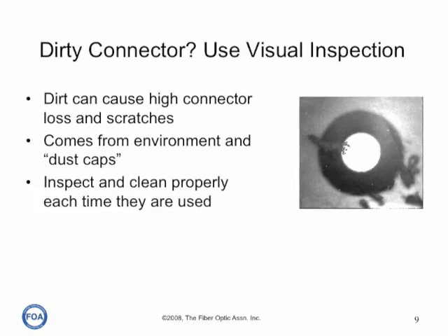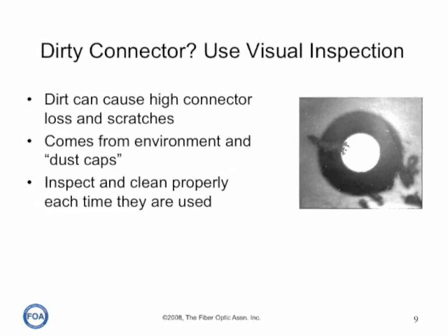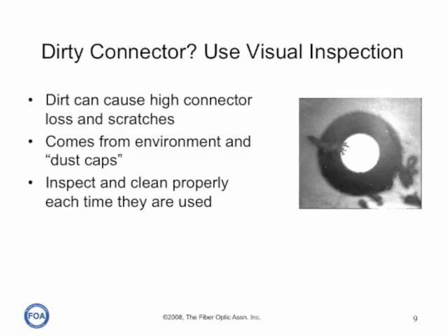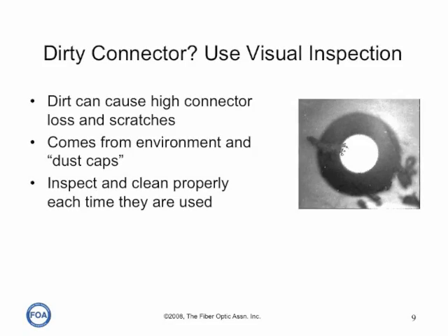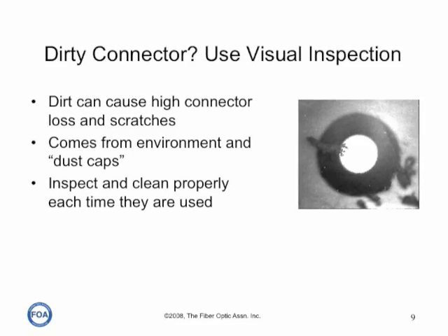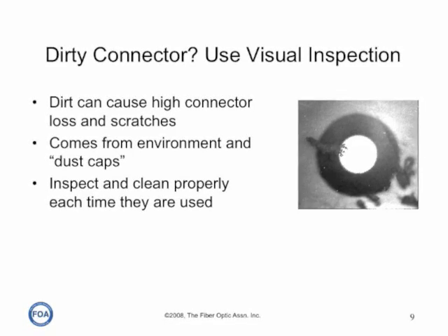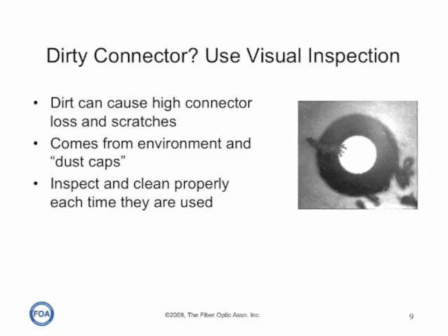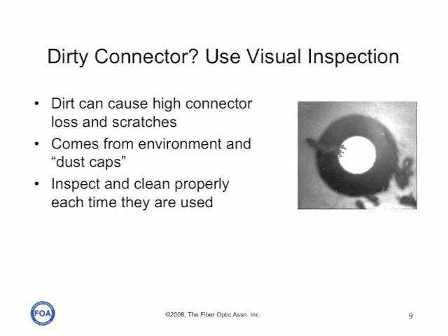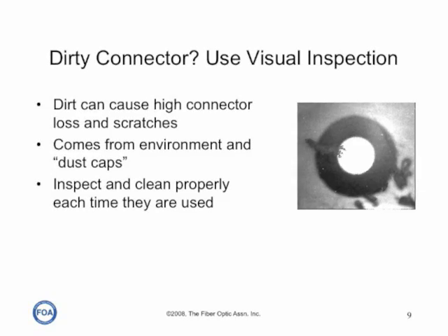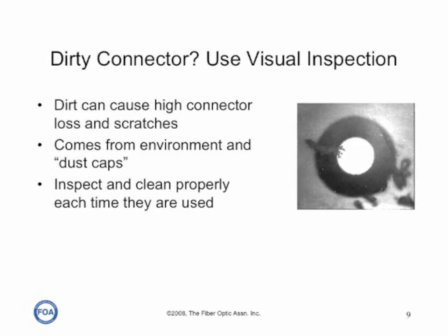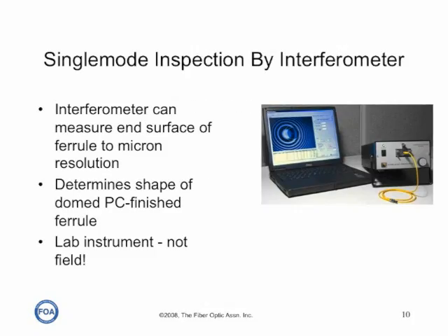These come from exposure to the environment and actually from what people call dust caps, which at least one installer I know claims are called dust caps because they're usually filled with dust. We inspect the connectors with a microscope and clean them properly, then inspect them again to make sure they're properly cleaned each time we use them.